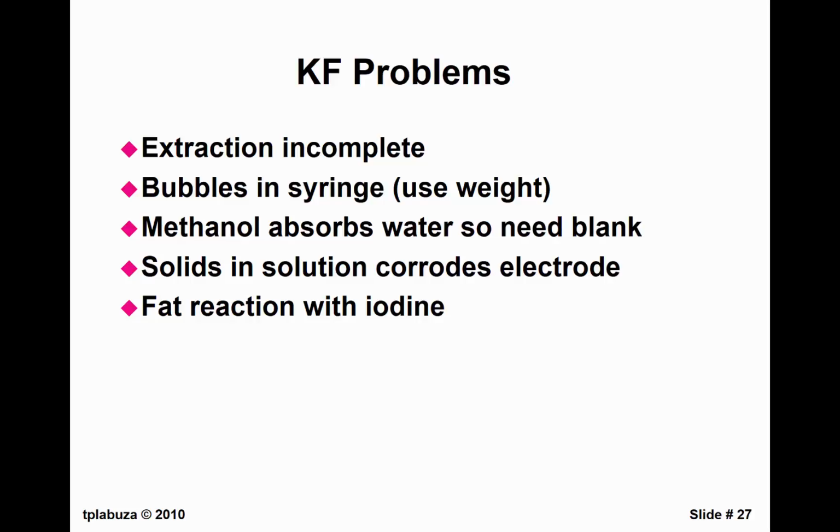So there's basically two steps. You extract the sample, you get it in a small shaking Erlenmeyer flask. You then open it, take a sample out, inject it into the Karl Fischer device and push a button, and in a few minutes it'll tell you how much water is in the sample. So it's a pretty easy system to work with. As I said before, the methanol absorbs water, so you need a blank.